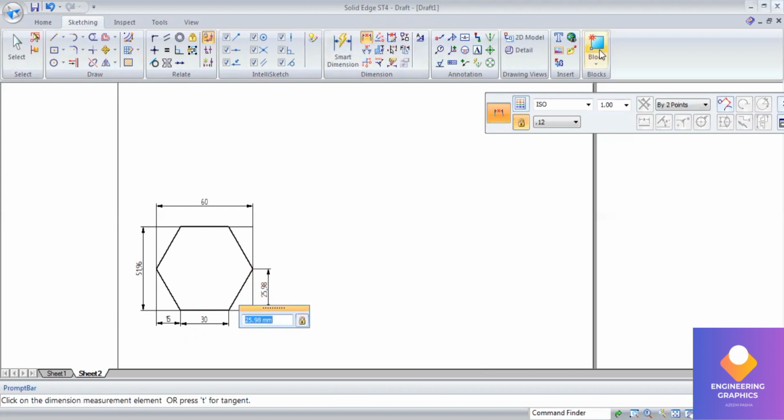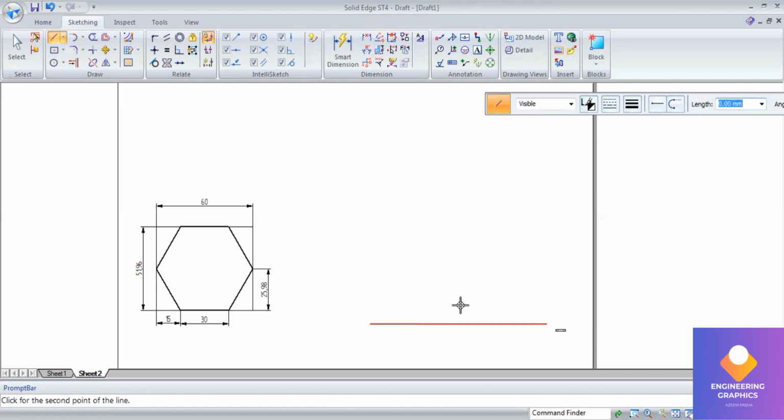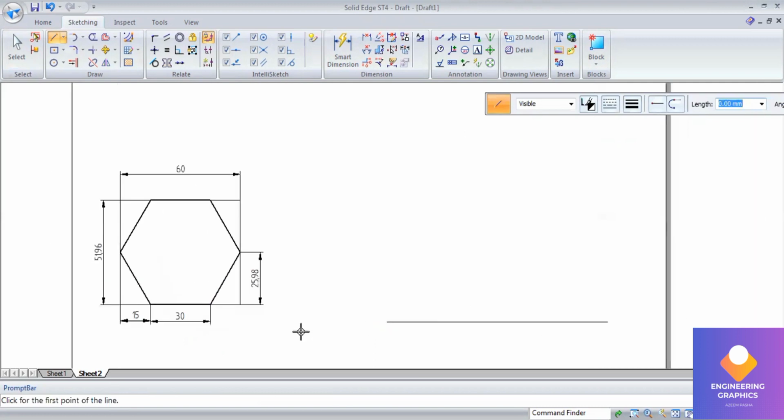Okay, so for the hexagon box with the box dimensions constructed, now I'll be constructing the orthographic of it. Take a reference line. From this reference line, construct a box for a length of 51.96, that is the first length, at an angle of 30 degrees.